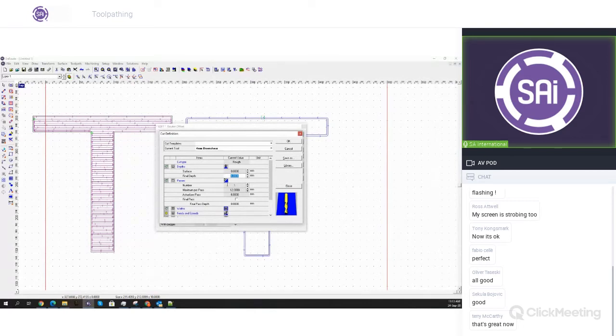The number of passes will always be defined based on the maximum per pass that your tool allows, but you are free to add in additional passes or change the maximum per pass here to, let's say, 3, and then EnRoute will automatically calculate how many passes it'll do and how much it will actually route per pass. So depending on the material, you can play around with these here.